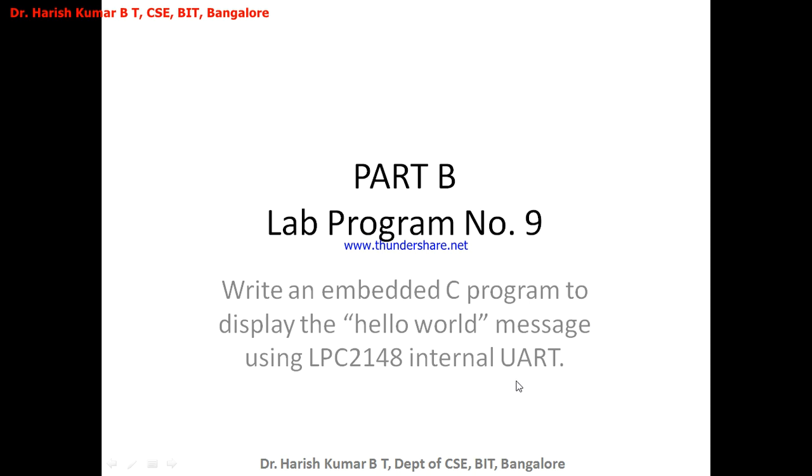the sender and the receiver. Synchronizing means that if the sender is too fast compared to the receiver, the sender is limited, and if the receiver is too fast in receiving the data compared to the sender, the receiver is limited. That is basically the synchronization. And here the synchronization is not done using clock cycles, but using a predefined agreement or a predefined contract, and by adding some additional bits. This is what I explained in the previous class on the UART, universal asynchronous receiver and transmitter.